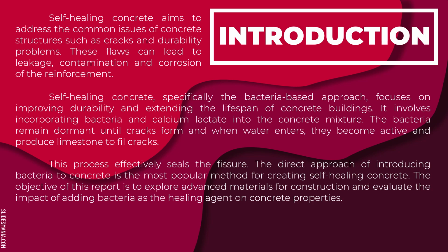It involves incorporating bacteria and calcium lactate into the concrete mixture. The bacteria remain dormant until cracks form, and when water enters, they become active and produce limestone to fill the cracks. This process effectively seals the fissure.